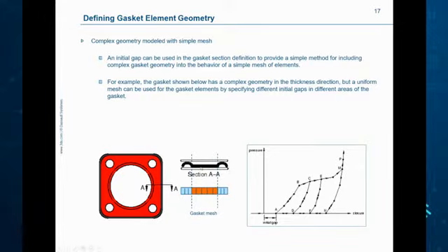But there's a region in the middle that has a gap. So I have to push the bumps down substantially until I hit the body of the gasket. So we try to model this cross section with a cross section as shown here at the bottom. And this would be our gasket mesh.